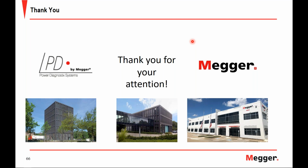But the coupling capacitor, preferably for offline measurements, in our product range from Power Diagnostics is 1 nanofarad, which is sufficient to detect problems from deep inside the windings. The filter is to be calculated according to the capacitance. So we need an approximate estimation of the coupling capacitor capacitance range, where we can then calculate the capacitive impedance and the required current, because the current is important for the filter.